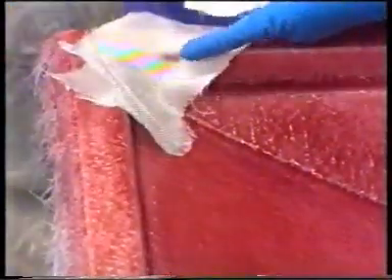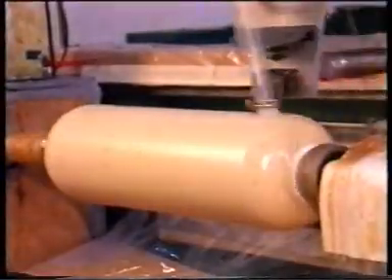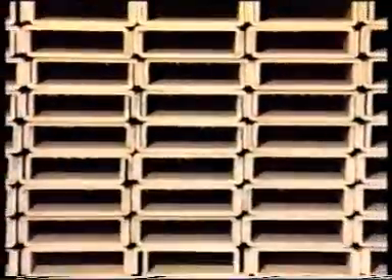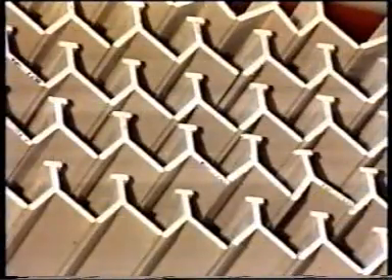Several different fiber materials can be used in the production of a single part. Fiber direction can be the same, varied angularly, or varied randomly through part thickness. Fibers and matrices are combined to form a multitude of composite products, often at a significant weight saving and sometimes cost saving relative to traditional materials.